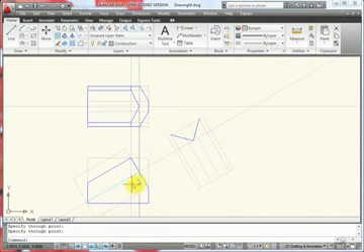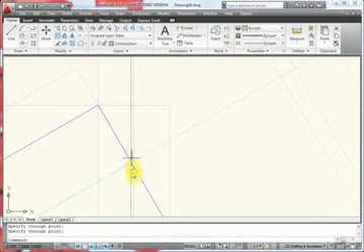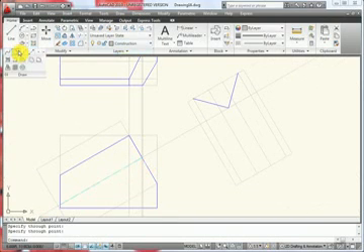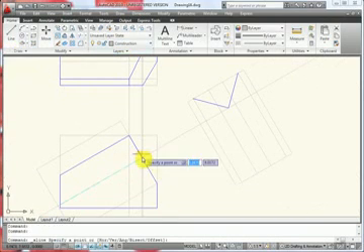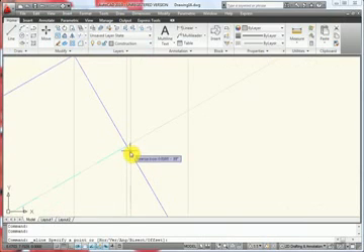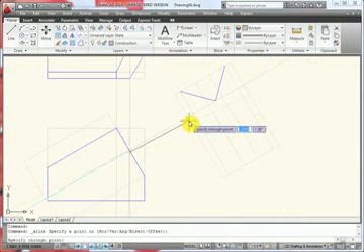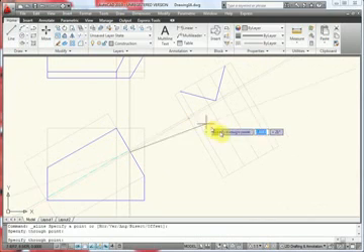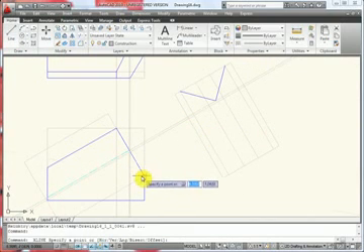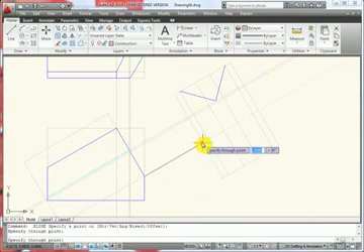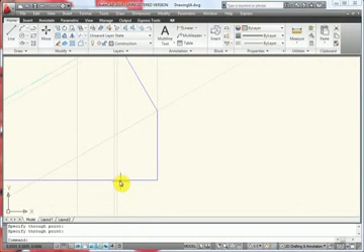And now I want to make some lines that are perpendicular to this surface but intersect this vertical line I just drew, and some other pieces of geometry. So I'm going to go to the construction line command, choose that point where it intersects here, and then snap perpendicular to here. I'm going to do the same thing with this point, and then again this point down here. Make sure it's the outside line, not the inside line.